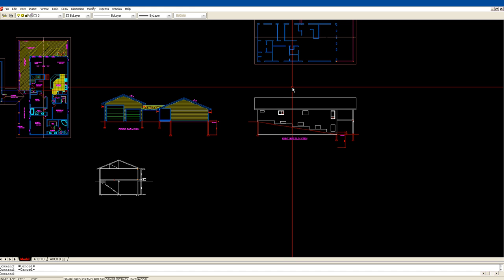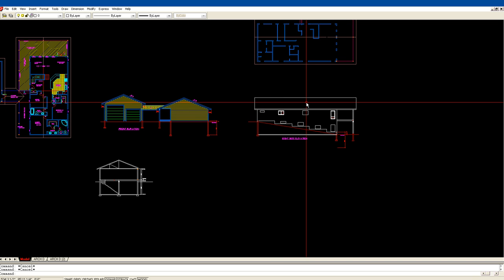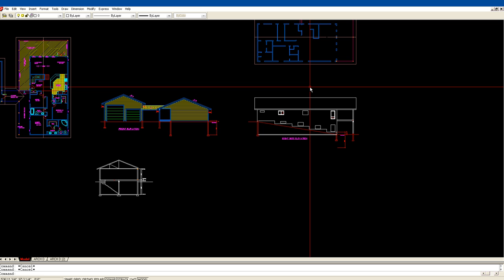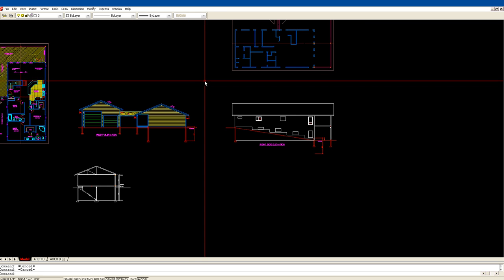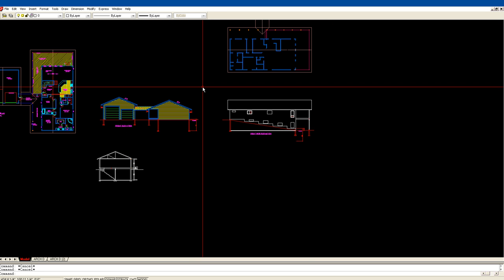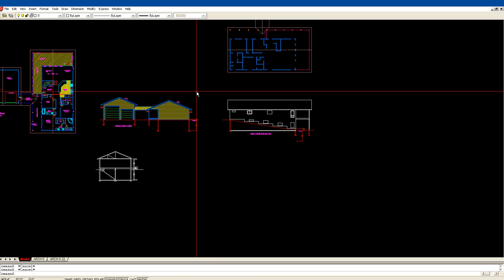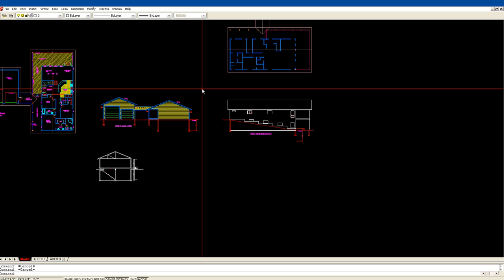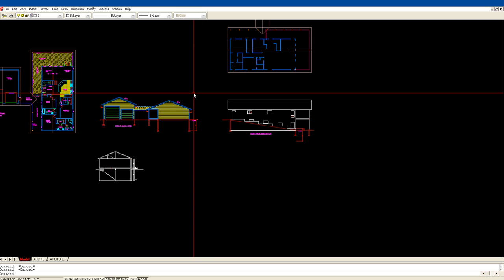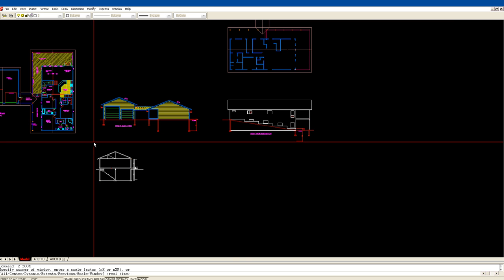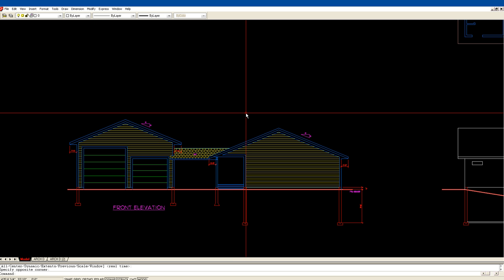Now we need another elevation, and again in a prelim it really depends. I might only show two, just exactly what you see here, the front of the house and the back of the house, because there wouldn't be anything really interesting or that you couldn't read from the plan. I don't want to go any farther than I have to, because of course I have to account for changes. In this case, I definitely want to show a rear elevation because that's the nicest, the most interesting elevation. So I already have the front developed, and I'm going to go to layer, turn hatch off,